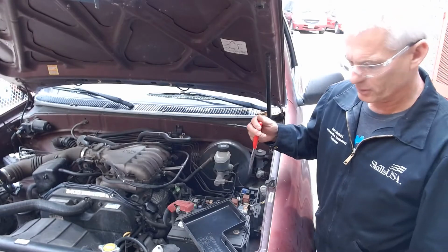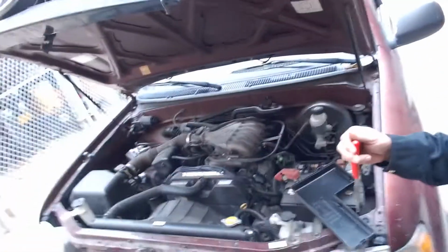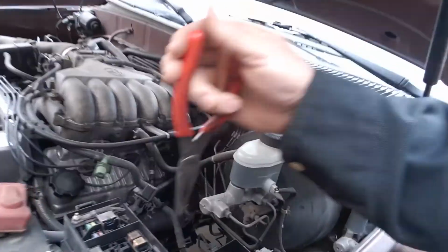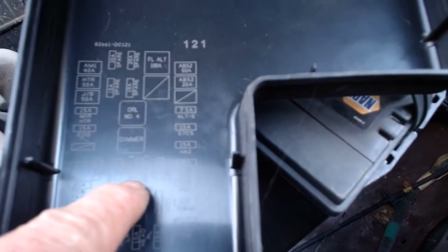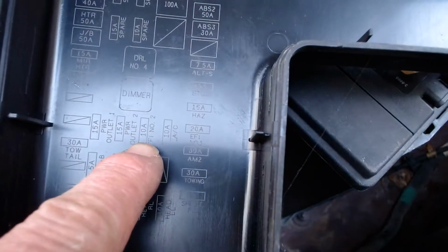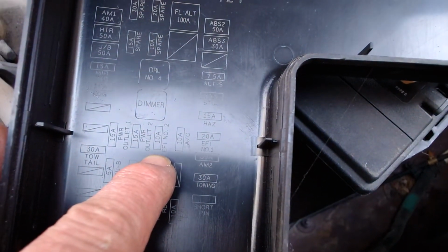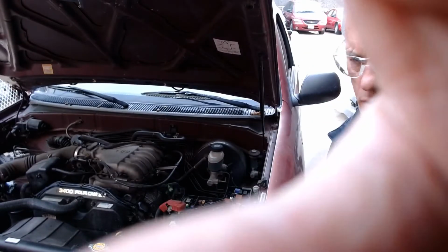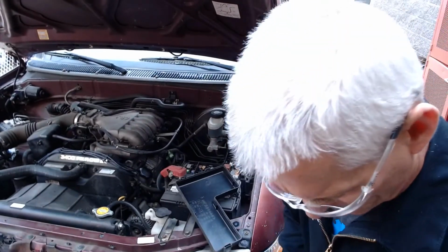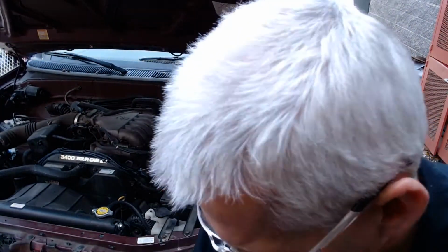Okay, so Mitchell ProDemand showed me that this EFI number 2 fuse should kill the fuel pump right here. That one right there. So I'll set it down on top of the battery. And that was this guy right here, EFI number 2. I think you can see it there. That 10 amp fuse right next to a 10 amp AC fuse, which would be the fuse for the AC compressor clutch. So now we'll see if that kills the engine. I'm going to back this up.